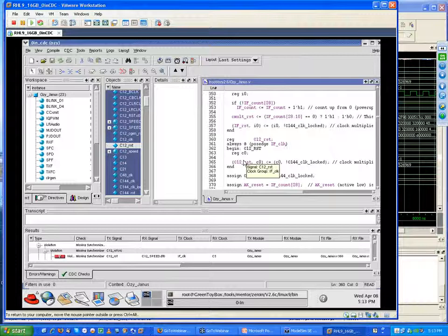A lot of the problems you have is it's not like you ever use an FPGA to its fullest extent. The problem is you get fuller and fuller, and most FPGAs are routing resources, and you start getting into timing issues because you start getting it too full. It has problems routing and stuff. Yeah, some of my DoD friends told me anything above 40% is pushing it for them. Yeah, I don't know where they're coming from because I've used a lot of different ones, and I'd say I push them more like 70%.